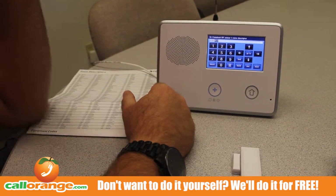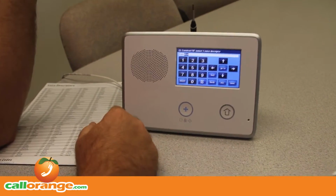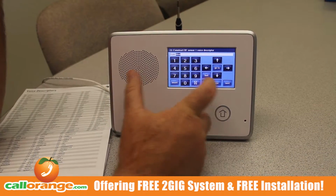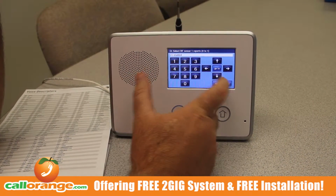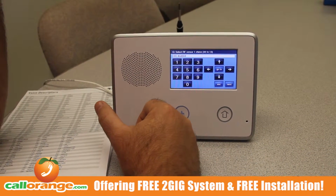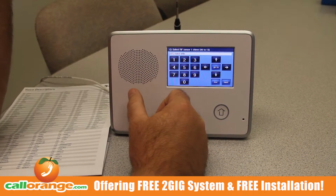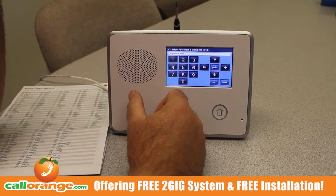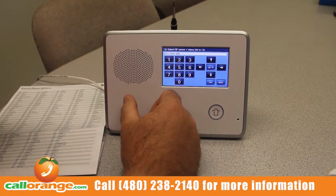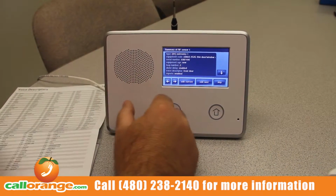I like doing that on all the sensors. So if there's a low battery or if there's a zone faulting, you don't have to go all the way through the house to determine what it is. You'll know it's the front door. You'll know it's the master bedroom window. Okay, press the down arrow. Everything's enabled. You get down to the chime. Okay, I like to put voice chime right here, voice. So now when the front door opens, or the master bedroom window is opened, or your child's window opens, instead of it beeping, it will say master bedroom window open. Down arrow, and now that one's done.